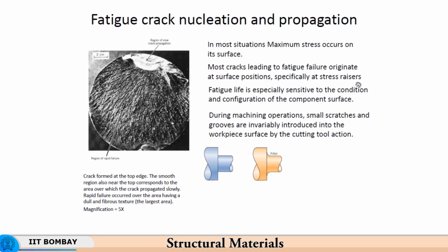Being a ductile material, although the fracture took place at a fast rate, still the nature of the fracture was ductile. But it is fast fracture because it happened at a very rapid rate. The strain energy was dissipated at a very rapid rate.